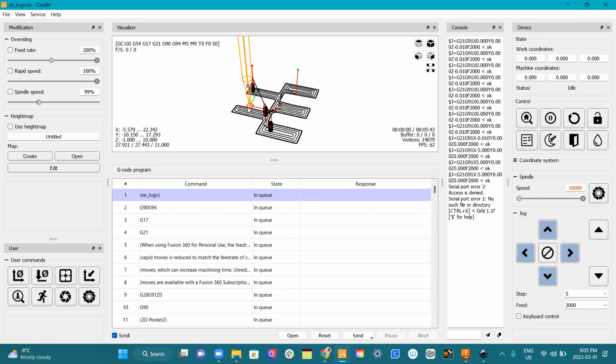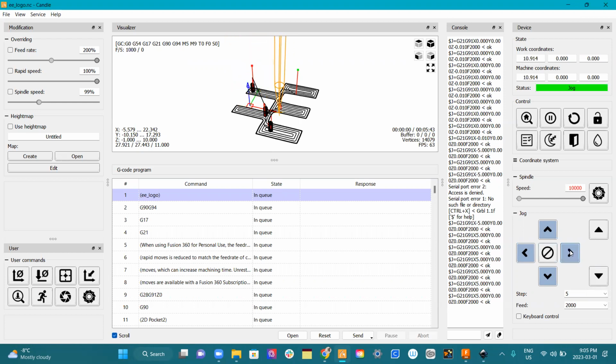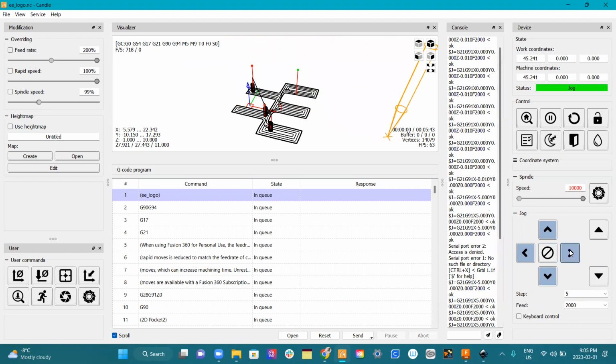I want it to be close, but not touching it, because if I just let it touch, it's going to just plow itself into the pine. So I'm going to lay that there and say I want it to go down until this is pinched. And so I set it to jog, and I slide the thing over till it's centered on that axis. And then do the same to the next one.